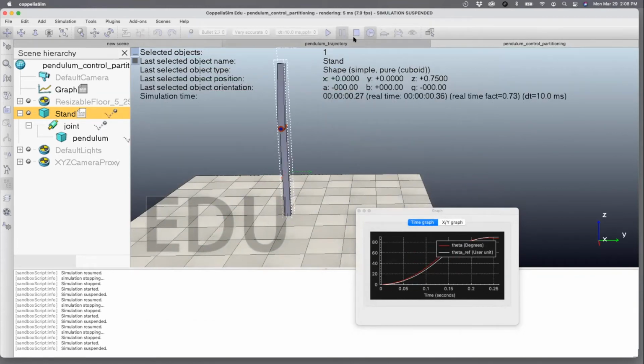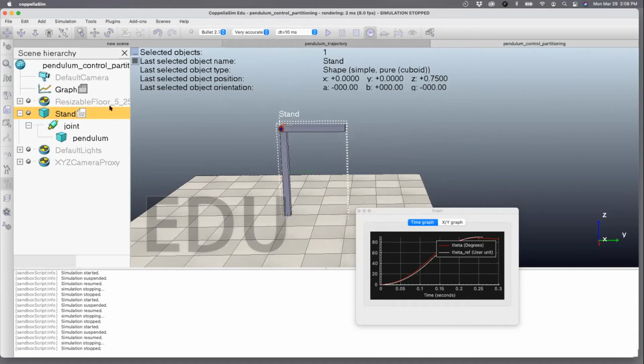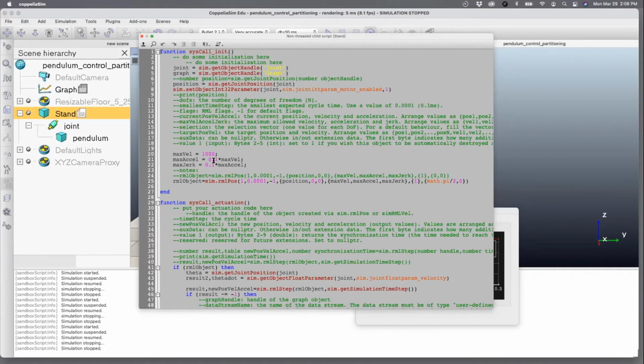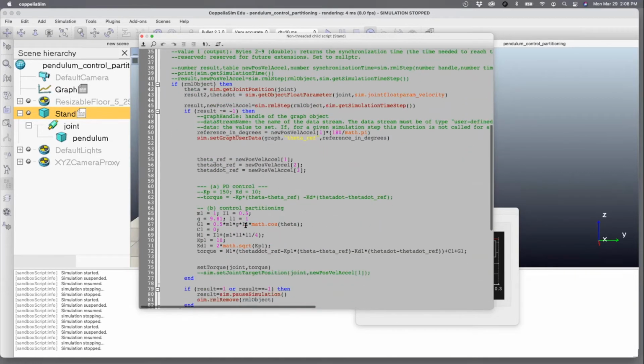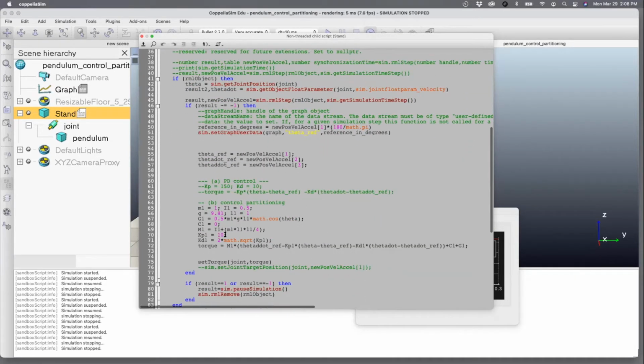This is decreasing. The other issue which you face here is you want to be accurate with this. So I note that I've changed this to 10 ms and not kept it as 50 ms anymore, because I can't use a big gain if I use a low bandwidth for the integrator. So I'm going to ramp this up to 100.